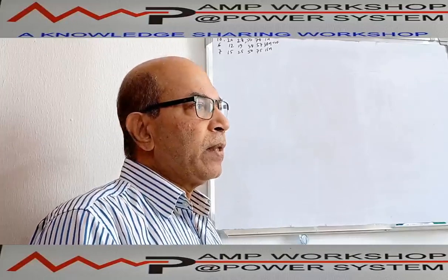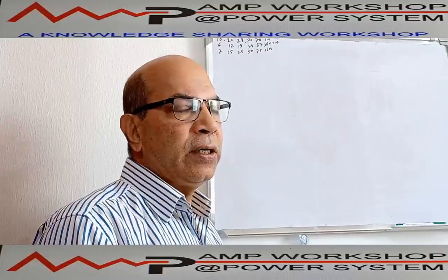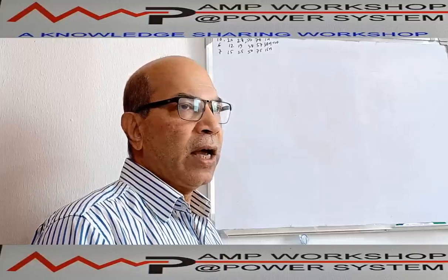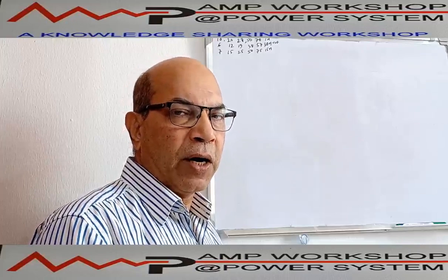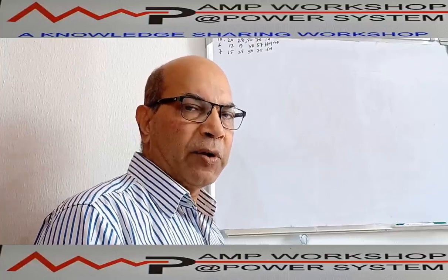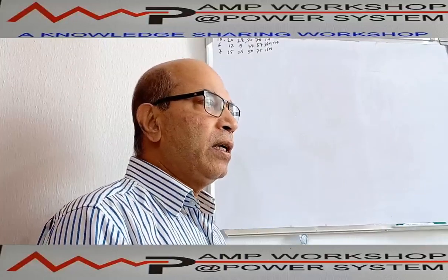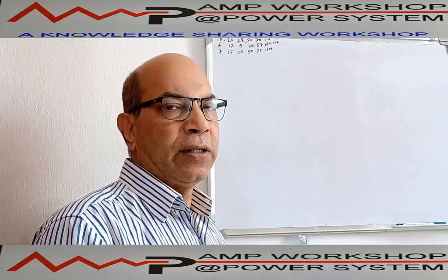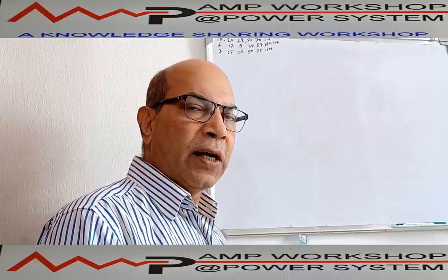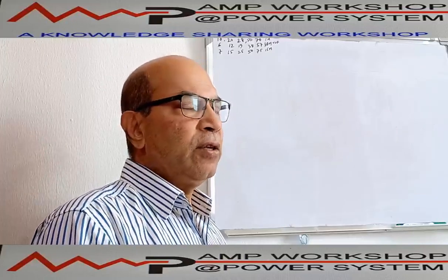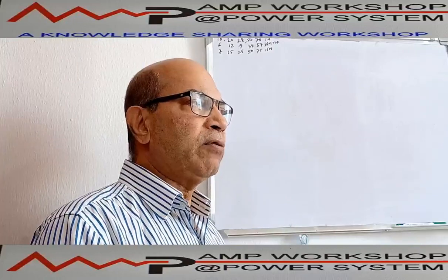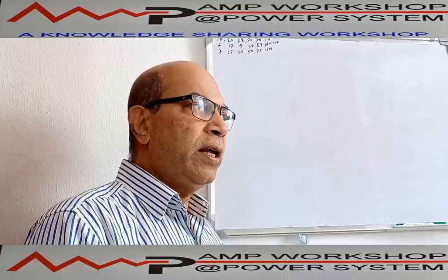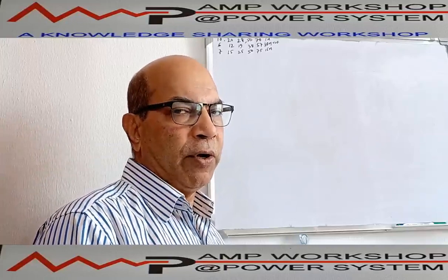That is one part. Second part, this conductor needs to carry current, but not all sizes of conductor can carry all sizes of current. So for each size of conductor, there is a current carrying capacity. So that is our purpose over here. For carrying a certain amount of power, what size of conductor is required? That is from the system engineering point of view, that we have to decide. That is the first part. So in deciding the cable sizing, first we have to decide what size of cable or what size of conductor is required to carry a certain amount of power from one point to other point.